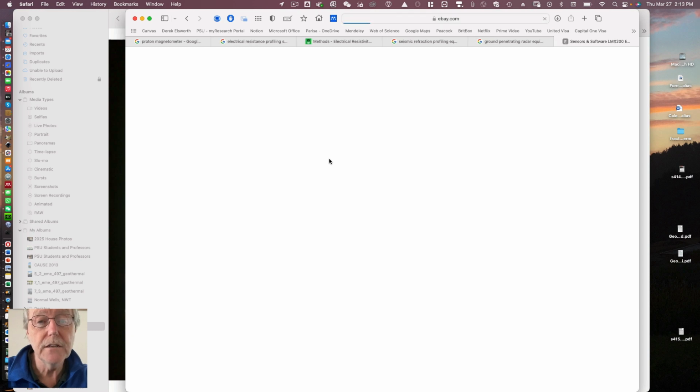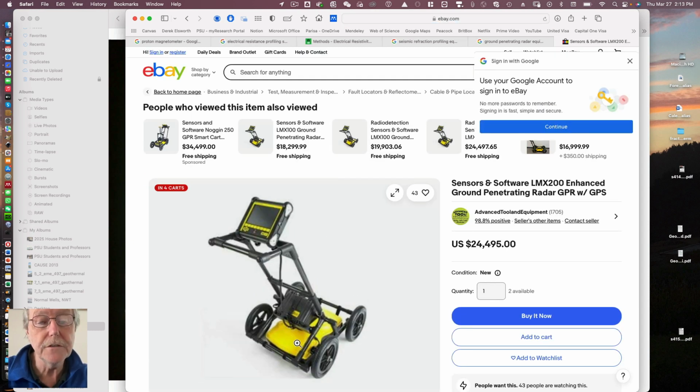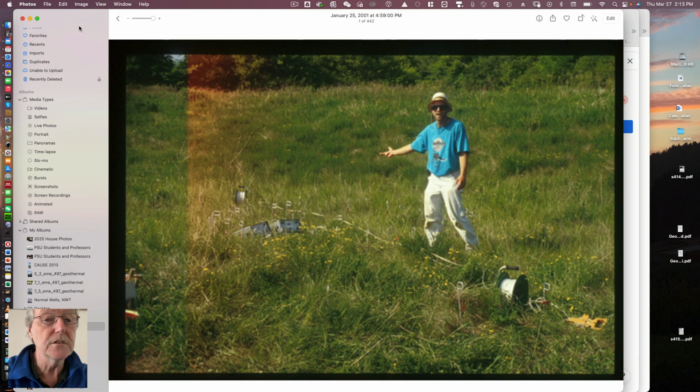It's just a trundle. It has a transmitter in the subsurface in this trolley. It has a receiver right in front of it. You push it across the surface. Sometimes they're on vehicles, on a quad bike or something. You get the signal up here. It uses GPS to locate where the individual pulses are sent from. Not sonar pulses, which are acoustic, but the individual radar pulses. So you end up with a continuous profile of the system.